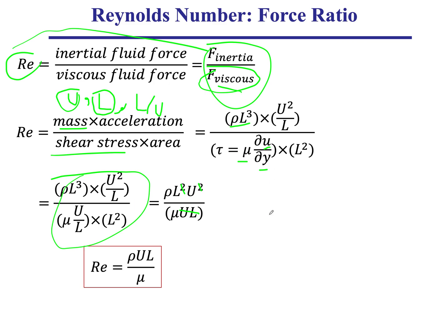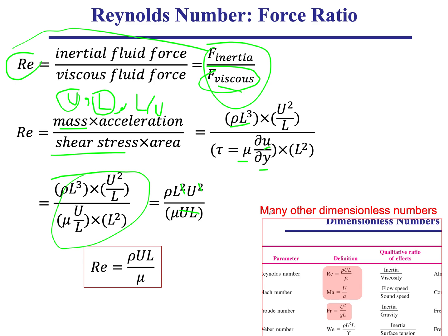Very good. So let's just recap for a second how we got to this point. Well, we started with the definition of scales: length, time, and velocity scales. Then we infused them into the Navier-Stokes equation. And after cleaning the Navier-Stokes equation, we ended up with a dimensionless number called the Reynolds number. And we just now, and in the previous lecture, described what happens in the limits of Reynolds number going to infinity or going to 0.